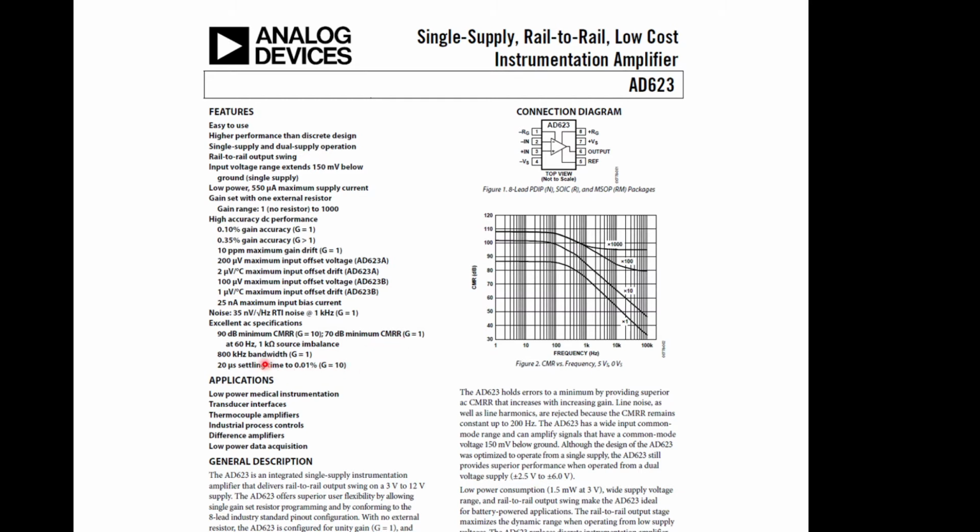And it's got an 800 kilohertz bandwidth, so it's not going to be looking at super fast signals, but for use in the ground where it's changing by the day, that's really not a problem. And if we turn it on and off, it takes 20 microseconds to settle down before you can start to take readings. So we have to bear that in mind when designing systems as well. So there's lots of stuff here, and then there's some words about it. So it's all wonderful. Is there anything else worth mentioning at the moment?